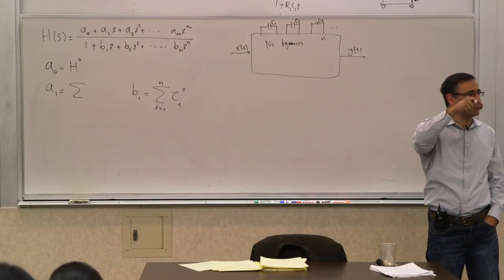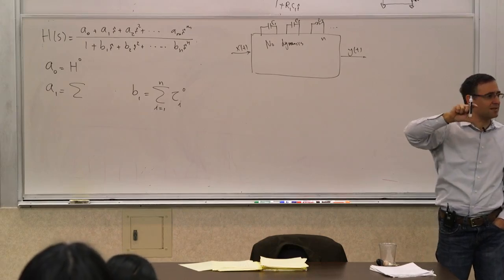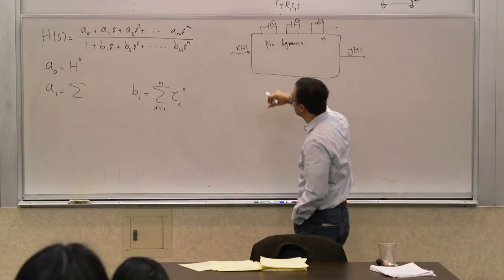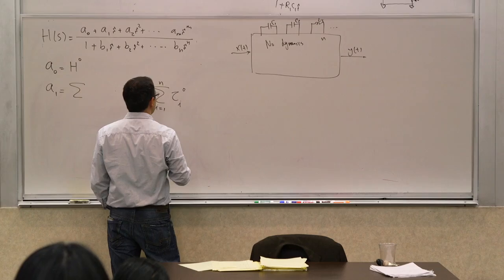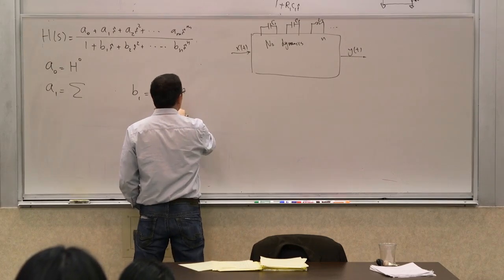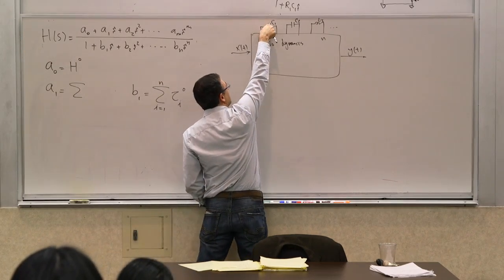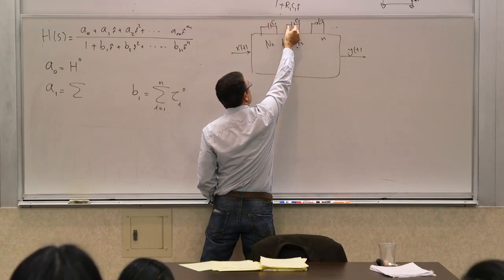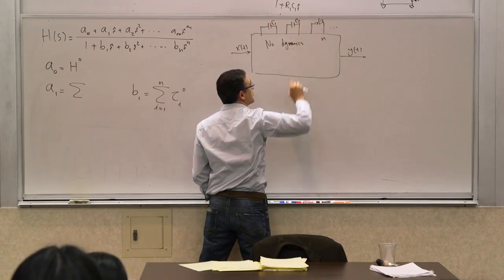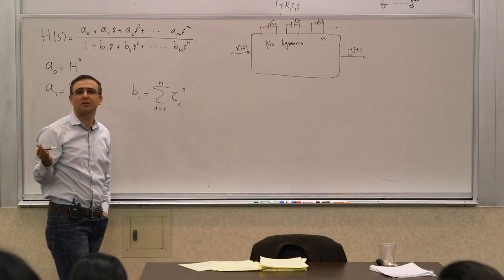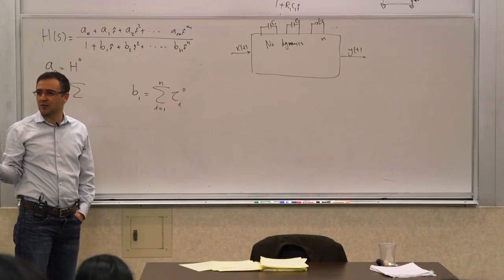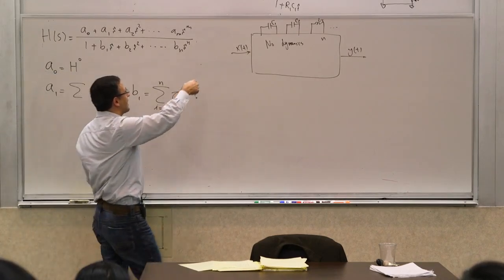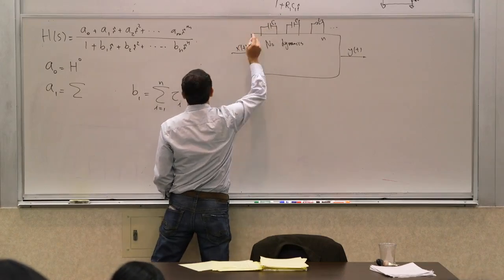So this basically covers essentially all kinds of circuits, because you can view the inductors and capacitors as things that are outside this box. So this is the sum of the zero value time constants, meaning that you look at this resistor across here when all the other elements are zero valued, meaning the capacitors are open and the inductors are shorted, because a zero valued inductor is a short circuit. You determine those resistors and multiply by the time constant.